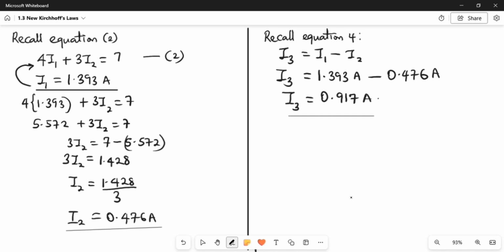So let's look at part B. Part B requires us to calculate the energy dissipated, the energy delivered to each resistor if the connection remains constant for 180 seconds. So energy delivered, energy E is expressed as IVT, or we can also express energy as I squared RT.